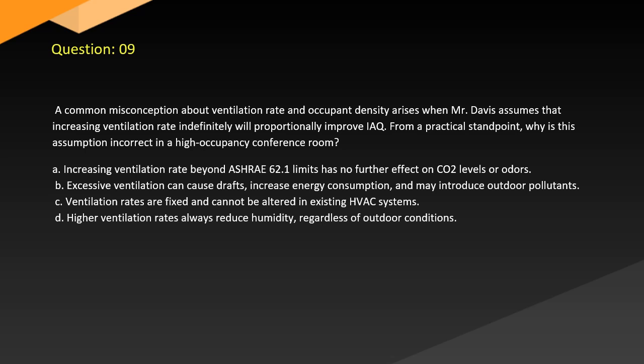Question 9. A common misconception about ventilation rate and occupant density arises when Mr. Davis assumes that increasing ventilation rate indefinitely will proportionally improve IAQ. From a practical standpoint, why is this assumption incorrect in a high-occupancy conference room? A. Increasing ventilation rate beyond ASHRAE 62.1 limits has no further effect on CO2 levels or odors. B. Excessive ventilation can cause drafts, increase energy consumption, and may introduce outdoor pollutants. C. Ventilation rates are fixed and cannot be altered in existing HVAC systems. D. High ventilation rates always reduce humidity, regardless of outdoor conditions.